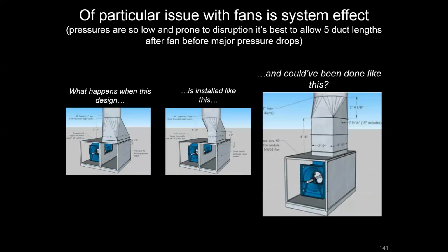And once we start recognizing these type of opportunities, we may even have gone back to that design and told our team or instructed the contractor that we really want a system like this, rather than horizontally discharging into an open plenum, having a reducer fitting, and then ultimately what ended up being this square fitting and this backward curve that has a high pressure drop associated with the large inches of water column being put out by this fan discharge. Why not vertically discharge straight up and reduce those high pressure drops?